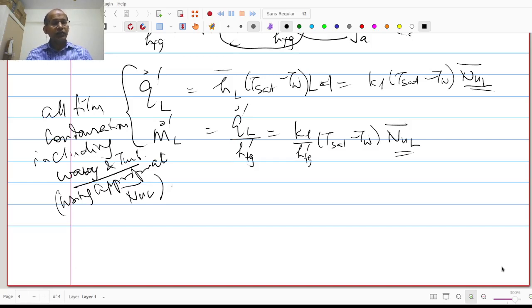So in the last lecture, we actually started with film condensation, and we looked at the mathematical formulation for film condensation using boundary layer approximation, considering the falling film from the vertical flat plate as a very thin film, and applied the boundary layer equations to the liquid film, and were able to derive an expression for laminar film condensation, the thickness of the layer delta, and from that